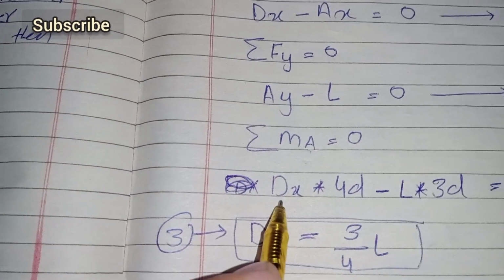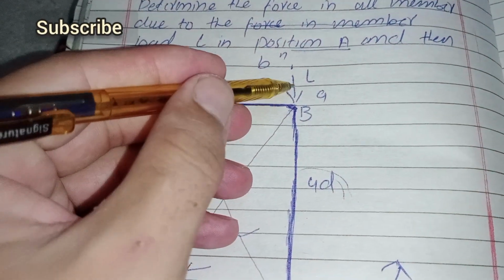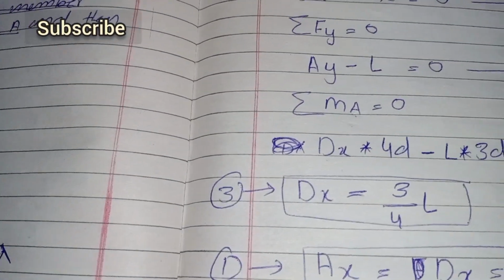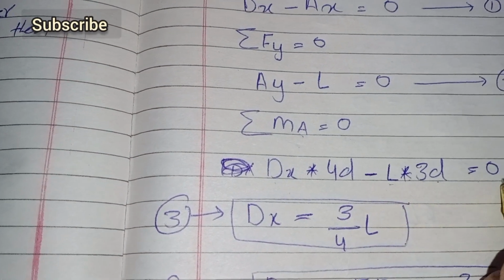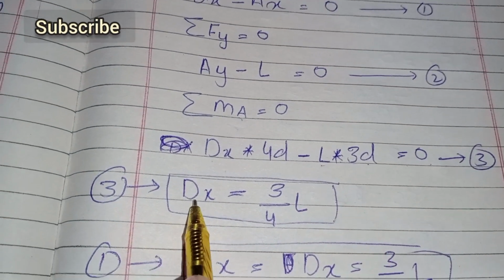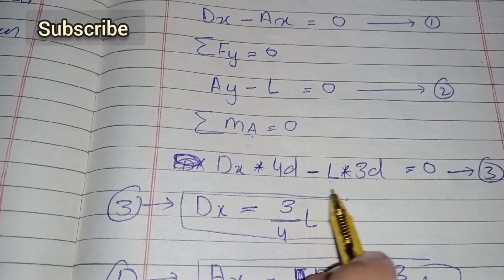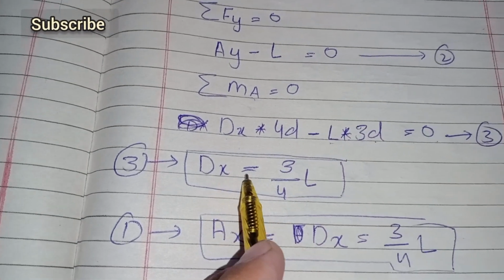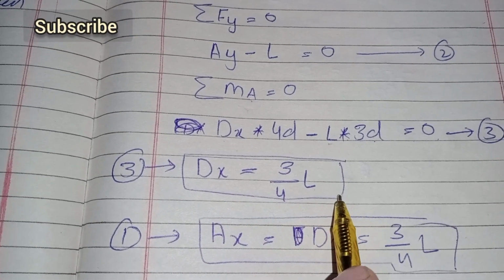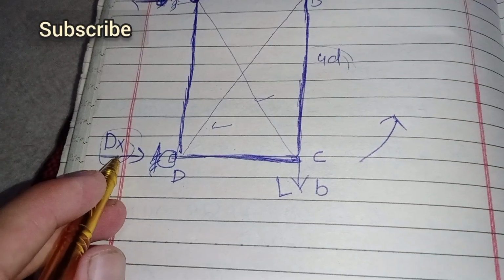So DX times 4d, minus L, which is this, L times the distance 3d, equals 0. Let's say this is equation 3. In equation 3, if you calculate this and move all known values to the right side, DX will equal 3 divided by 4 L, which equals 0.75 load. DX equals 0.75 load.